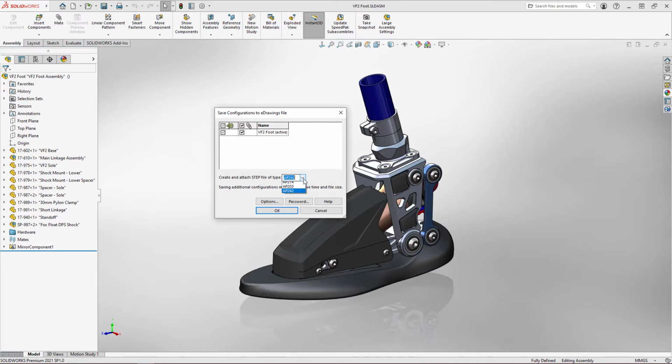Now the attachment is a step file, so one of the 3 formats of step file. This is useful if the model needs to be sent to a manufacturing team, a stakeholder, and they need to access a neutral format file for producing manufacturing data from. I'll leave that on for now to show an example.